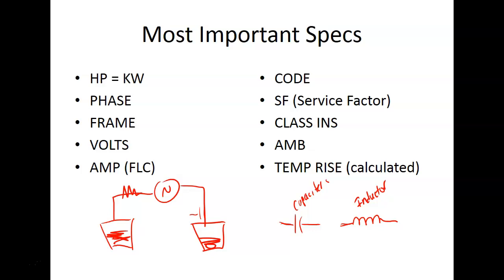It's new on the motor: to increase the efficiency of the motor, they'll give you a code where you can calculate the size of capacitor you need to bring it back. That's not on this PowerPoint, but it's new on your new motors. They always strive to make motors more efficient. By the way, a motor's power factor is better if you run it at rated horsepower. People buy a 10 horsepower motor and run a 5 horsepower load, and they're actually drawing more current and getting worse performance.